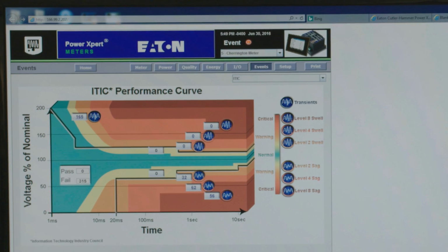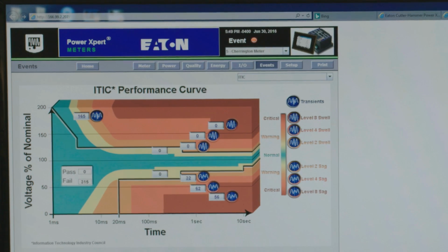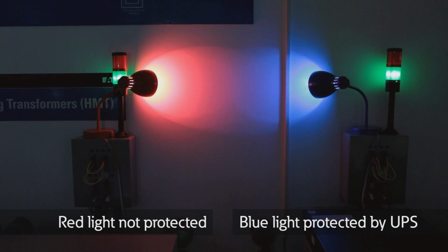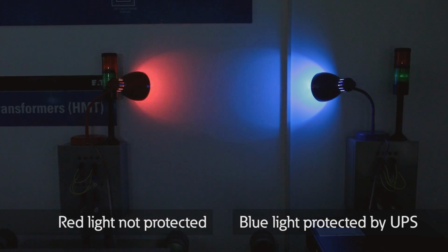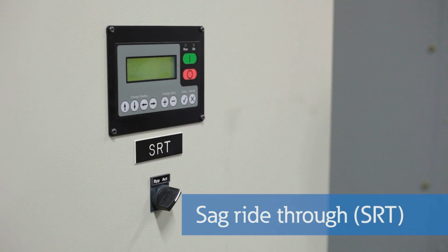Of course, there are no guarantees that those events will repeat, but with enough statistical data, like this ITIC curve, you can feel pretty comfortable that you understand the issue. Then you can select the size and type of the solution for your system. These solutions range from small ride-through devices through large UPSs and everything in between, each with different technical advantages and cost benefits.